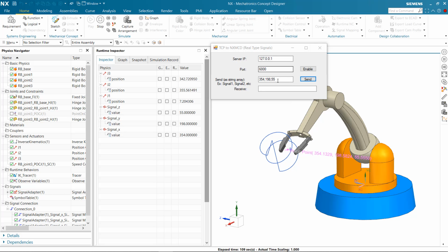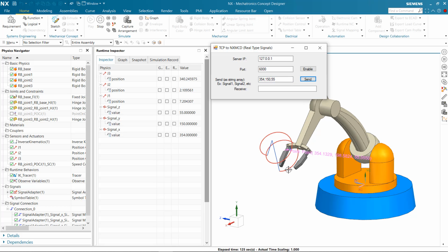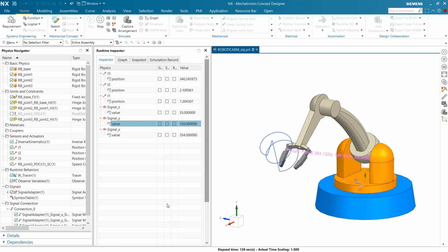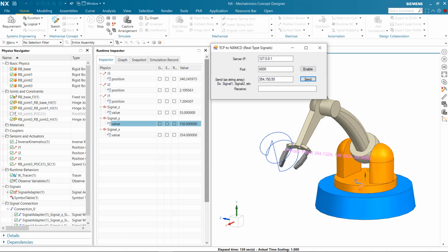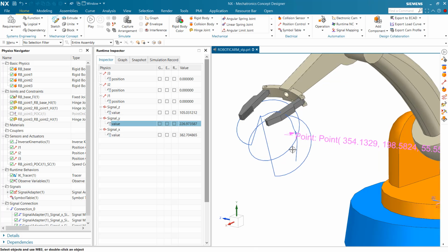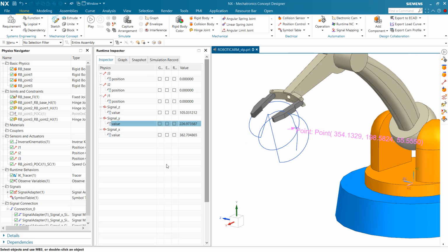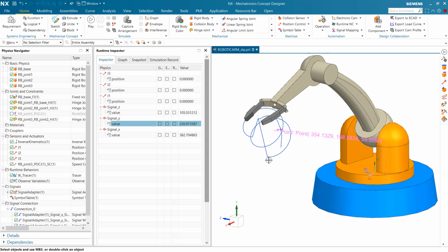So I can definitely try to play around. For example, if I put another value, let's say I want to lower the tool center point in the Y direction, so I'll just reduce Y coordinate to 150. Yeah, you see that it is now over here, and this value has been mapped to the client software. So I will stop for now, and I will explain to you the methodology behind how we can build the TCP server, what are the conversions occurring in the background, and so forth.